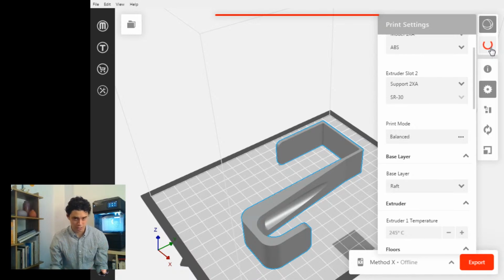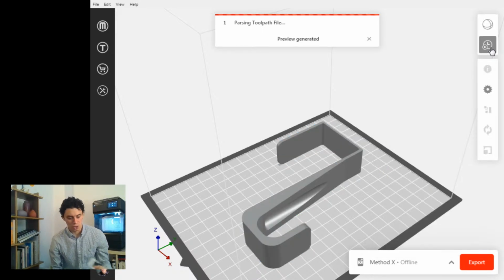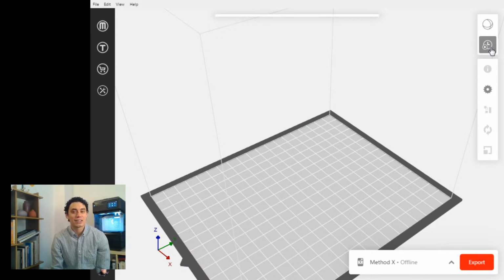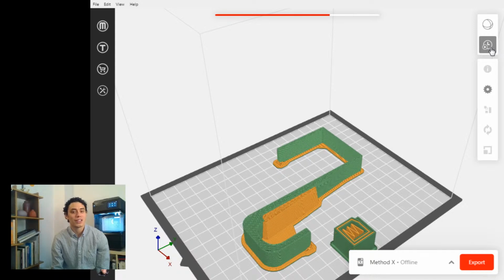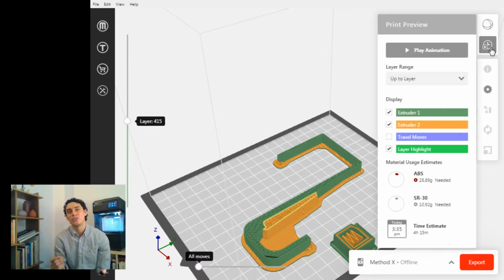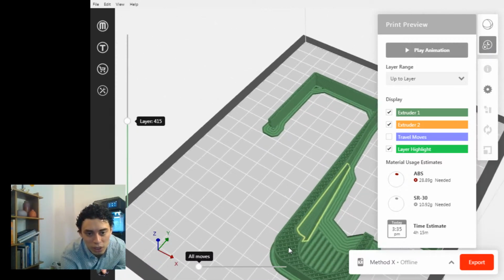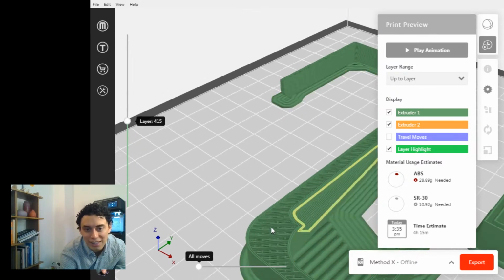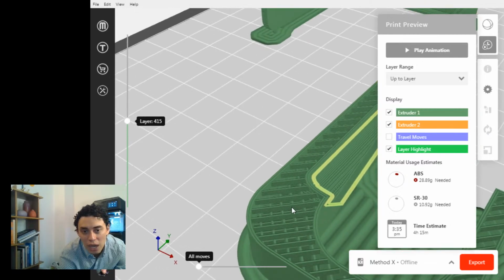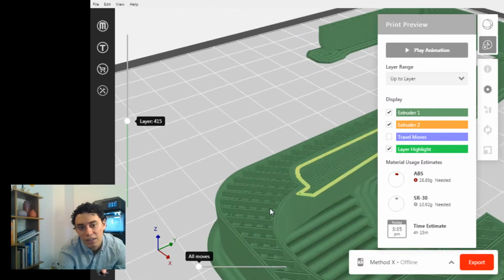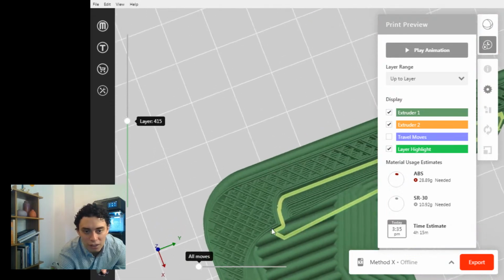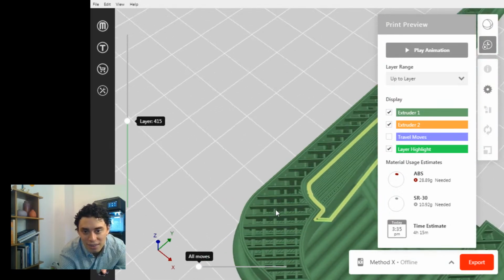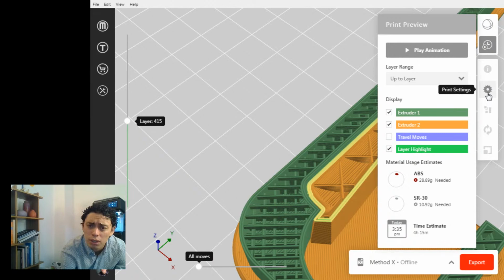So that's the density, right? I had a friend asking me over the week, how do I change the density of the part? How do I make it a little bit beefier? The beefiness doesn't necessarily equate one-to-one to the infill density. As I was saying, this one is 20%, and you can see this is the pattern being generated, how much material I'm going to have inside of this part. It creates this lattice pattern, this crisscrossing path that we called interwoven, I think.